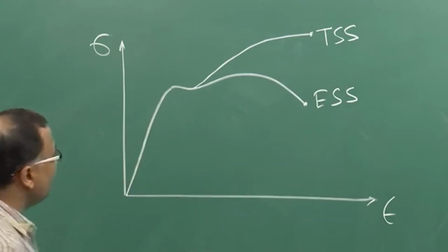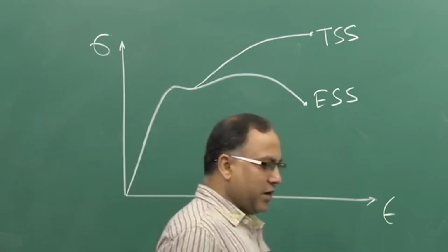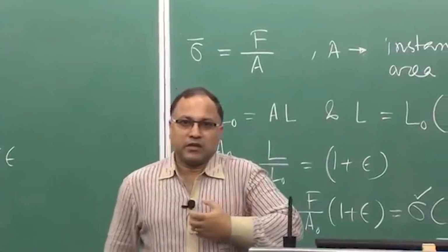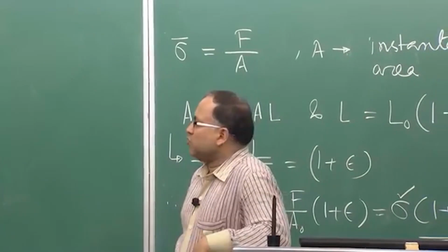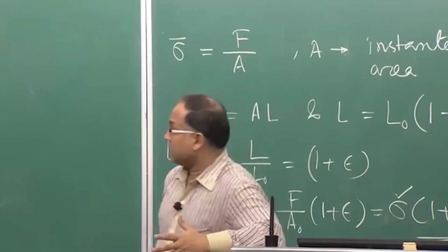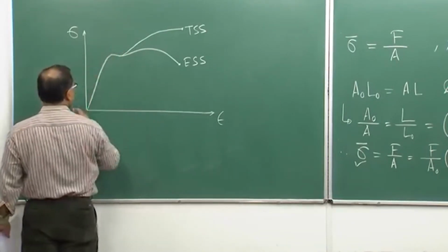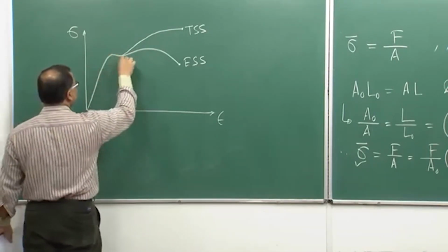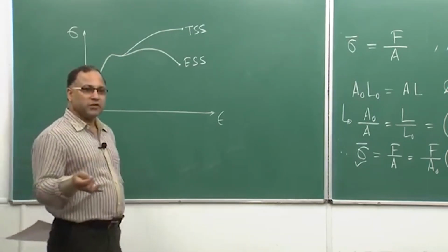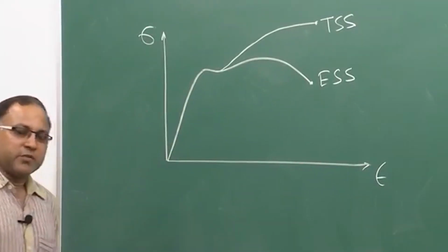So, now if you look at, up to this point, as long as you are dealing with a small strain problem, then engineering strain and true strain will not make much difference, right. As long as you are within this range of strain, you see that same curve, true strain and engineering strain both are predicting almost similar behavior or similar stress strain behavior.